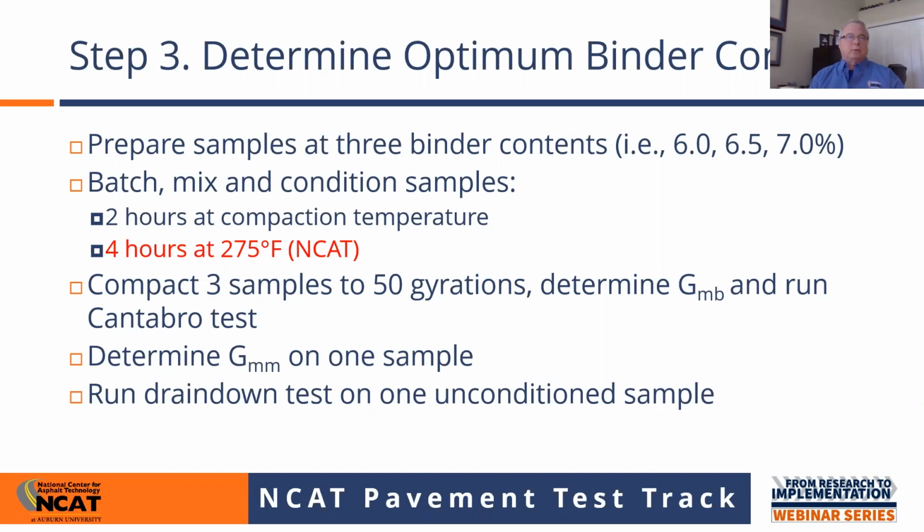And what we did is we focused more on longer term aging, because with absorptive materials, you end up losing a lot of that effective asphalt if you don't get it conditioned properly, particularly with an open graded mix like this. So R30 has that caveat that if you're going to do performance testing, it's 4 hours, I think, at the compaction temperature, but we standardized it at 275. That was a key thing that we did, and that's why I've got it highlighted in red.